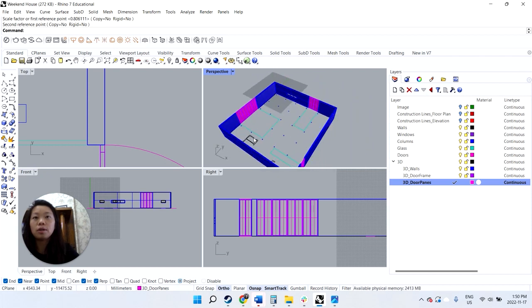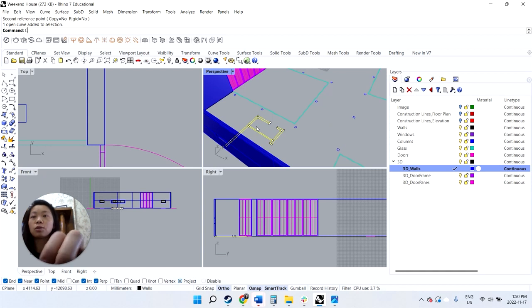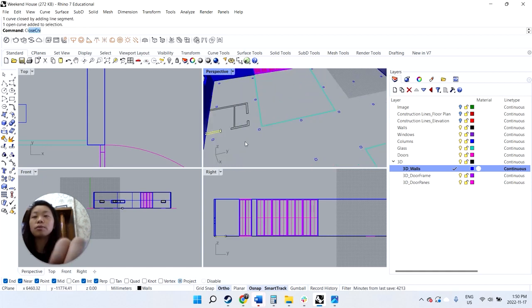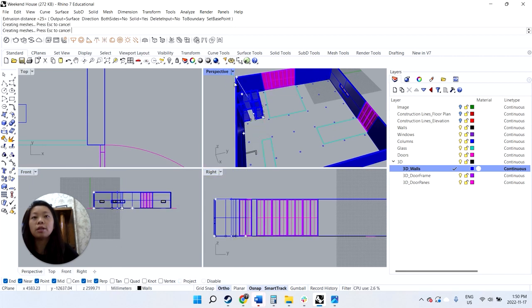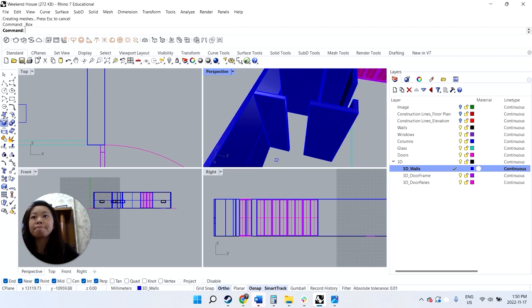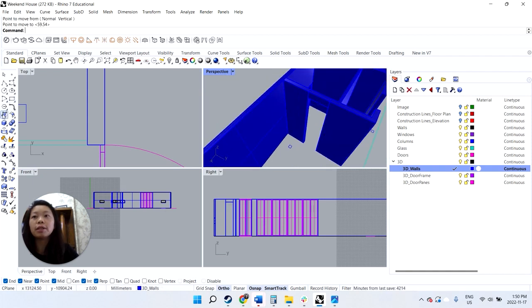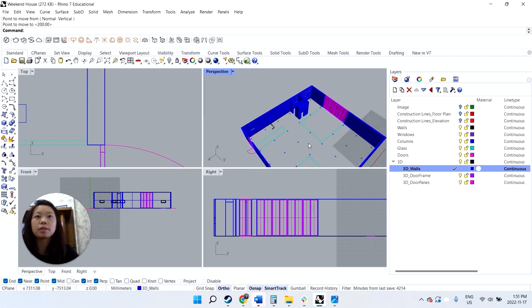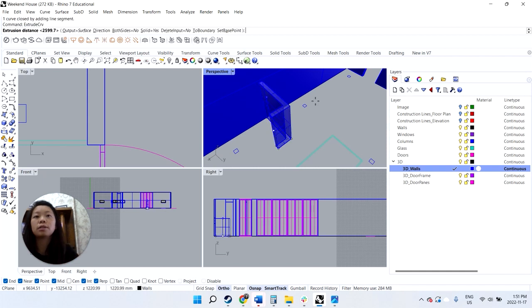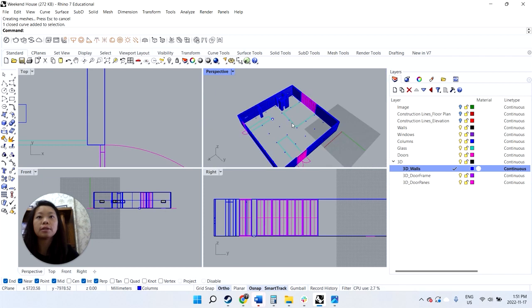So again, we see the walls. Next, oh, I forgot to do these ones, so maybe make sure that it's closed. Make sure this is closed. And then we can extrude those walls up. Unchecking project on. There. We might have a bit of a doorway, so see how high are these walls? 200. Because I believe these are doors. 200. Right. And then, all right. So that's good.